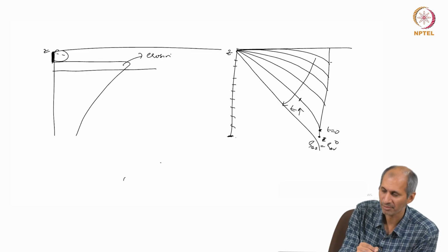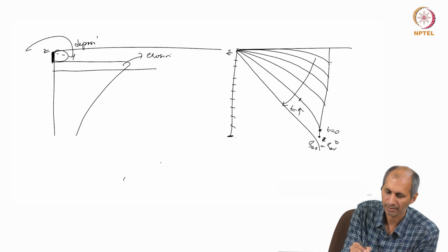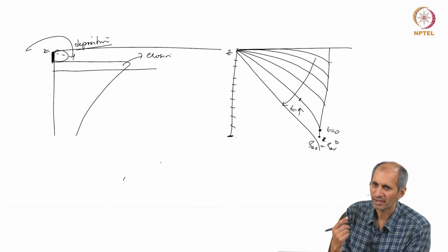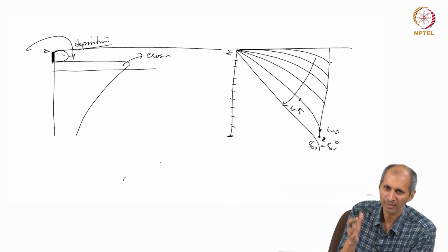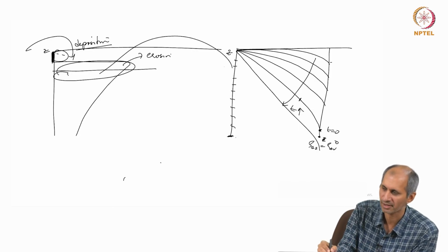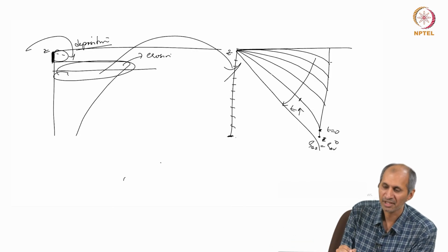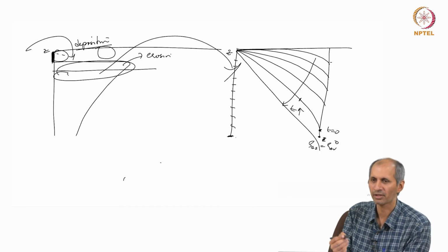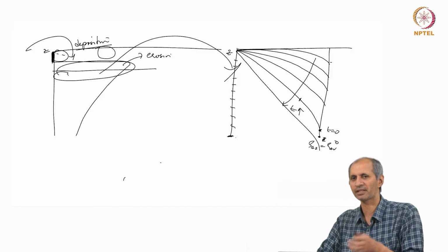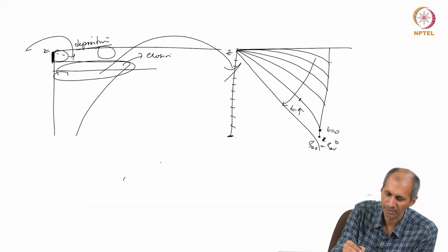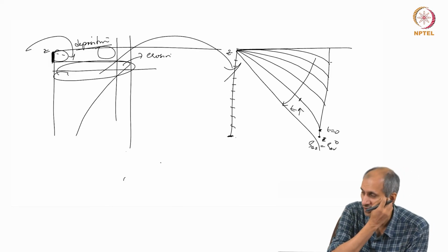But because erosion is happening somewhere else, that material can get deposited here. This happens a lot when you have heavy rainfall: erosion happens, a lot of sediment gets carried away, and it gets deposited elsewhere. That is the reason why you cannot go to a sediment and take a top layer sample. I cannot take a small bucket, pick the top layer and declare that there is no contamination, when there is contamination sitting below. That is why you have to take a core sample to a certain depth.